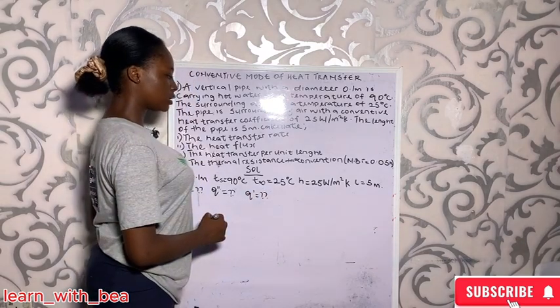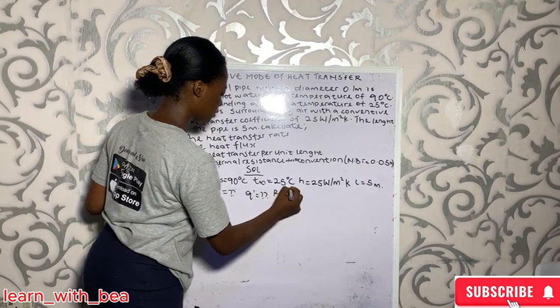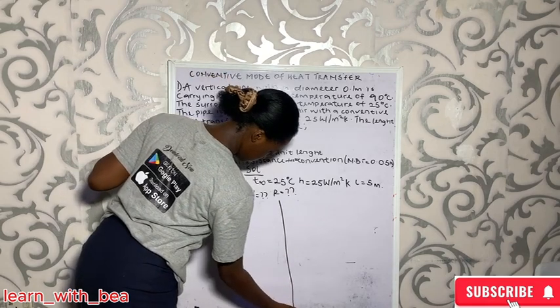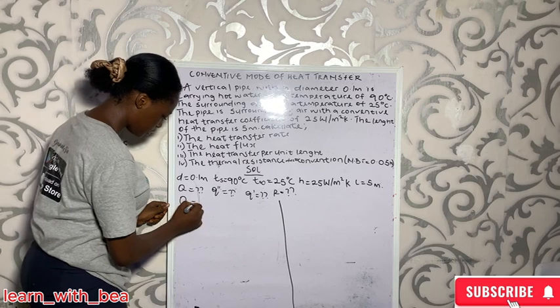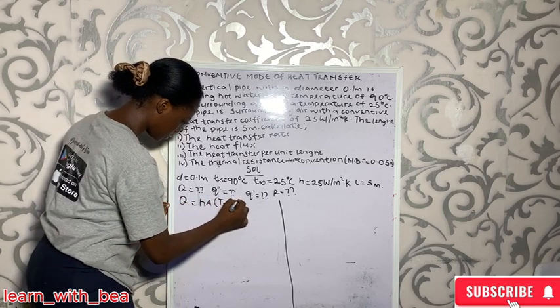Then the thermal resistance due to convection, that's our R. So these are the things that we asked to look for. So let's get right into it. If we want to get our Q, what's the formula for Q? Q = hA(Ts - T∞).